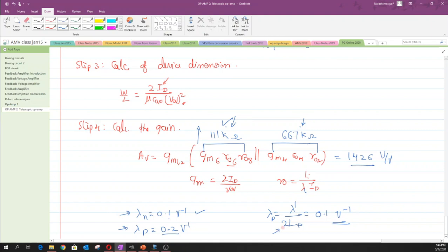But when we double only the length of a PMOS transistor, obviously the gm will also get modified, right? The gm is proportional to the W by L factor. So when we just increase the length of the transistor, then obviously the gm of the structure will be reduced by half. But we don't want to change the gm value of these transistors.